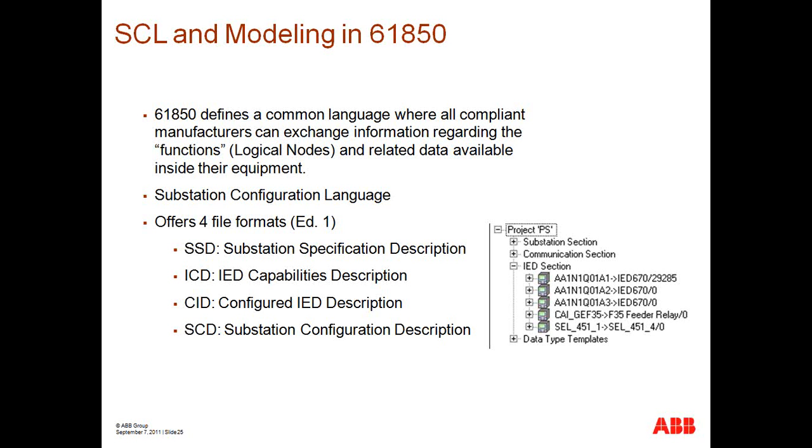So what does it allow us to document? Well, it allows us to document the functions that are available within an IED. It allows us to document the one-line diagram of the substation. It allows us to document the association of those IEDs to locations or bays within the substation. And it also allows us to document the connection between IEDs.